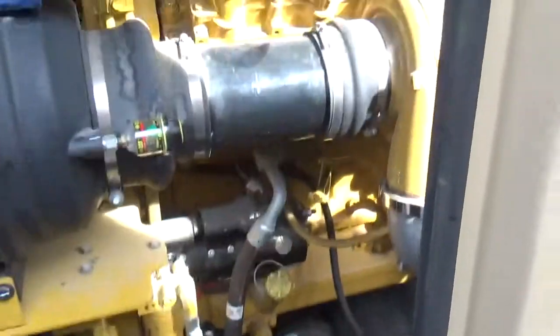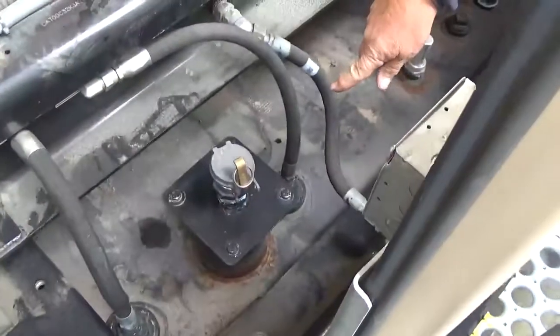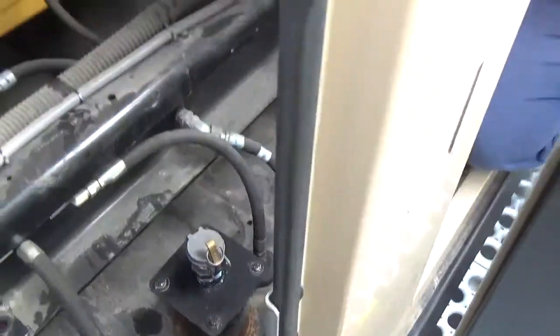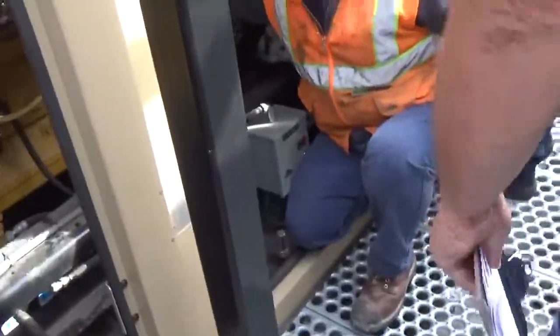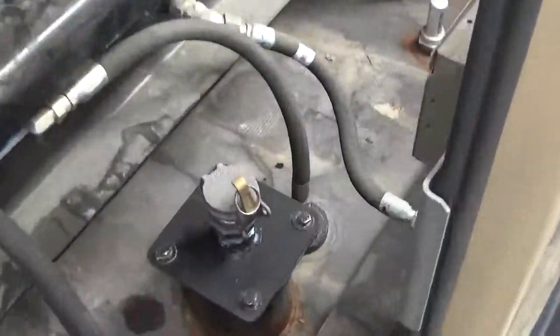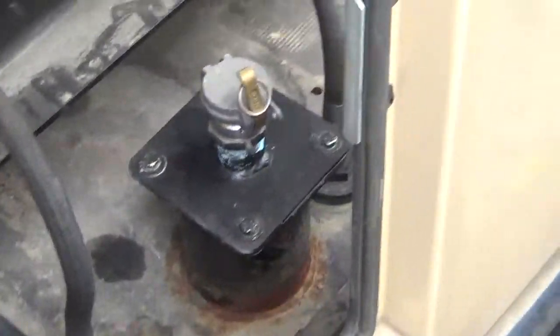And for some reason, if your fuel transfer system isn't working, obviously you can manual fill there with, like if this one quits but that one's working, you can set up a pump and suck out of that one and put it into this one or whatever you want to do. That's what that is. And it's got a lid on it, obviously, and a seal, because if you overfill it with your primary system, it'll come out of there like a rainbow if it wasn't a sealed cap.